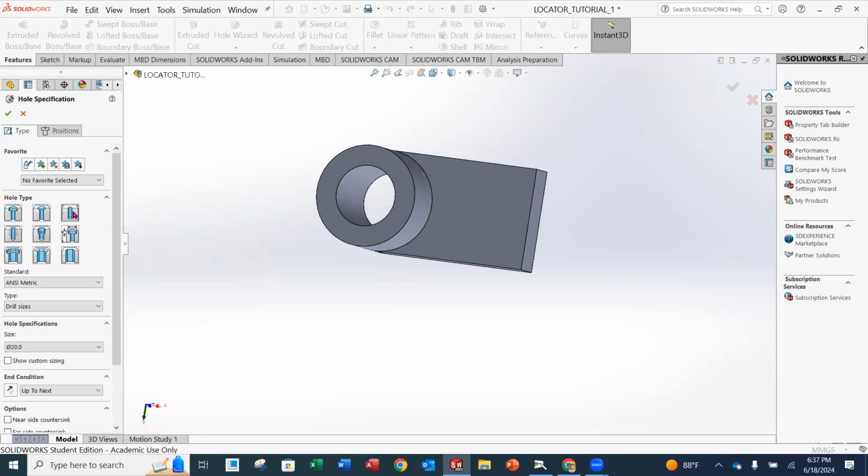So we're going to click on that. Make sure it's activated. It kind of changes the background. You can see it's selected, but just make sure it's selected. And then you're going to notice that it says what the standard is going to be. If I arrow down here, there are a number of different standards, and we just want ANSI Metric.